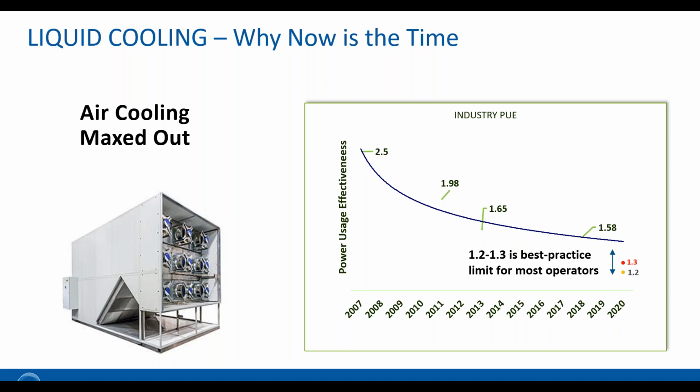Even if I look at the most aggressively optimized air-cooled facilities, we are looking at PUEs of 1.15 maybe in moderate climates such as London, to 1.2, 1.3 depending again on climate, on location, and choices of technology and also operational regimes. What's the temperature band people are willing to put up with? To go beyond that, we would need to see much more aggressive behavior when it comes to ASHRAE envelopes. So we would need to see the adoption and excursion into ASHRAE allowable ranges.